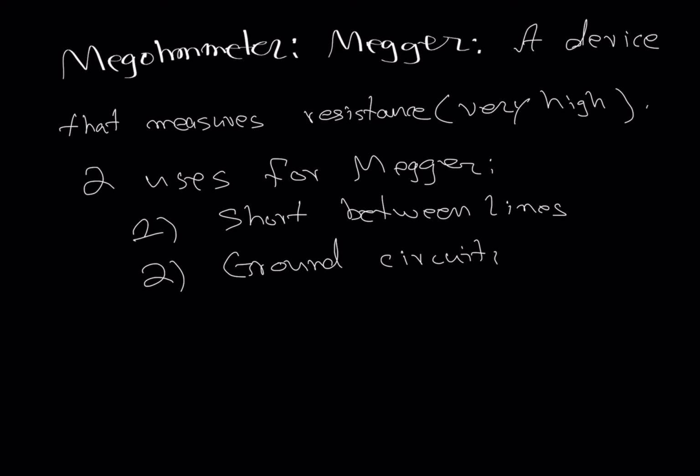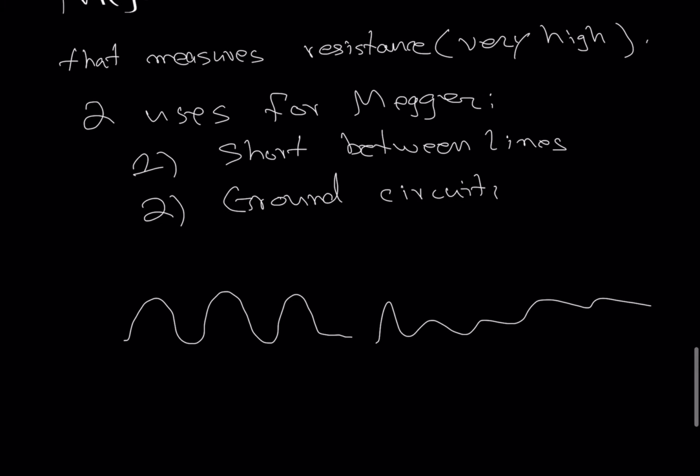So what does that mean? For example, if you're running a 3-phase motor that runs 480 volts, each phase should be independent of each other. But if for some reason the motor is acting up, making a noise, burning, getting hot, that is a good indication to open the lead of the motor, kill the power, and connect your Megger to each lead. You have only 2 leads, plus and negative. Connect one to one lead and the other to the other one, and read the resistance.